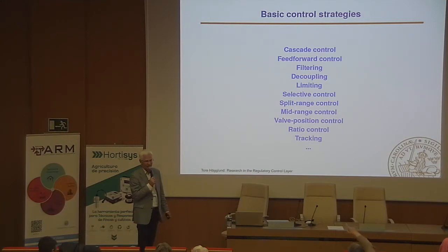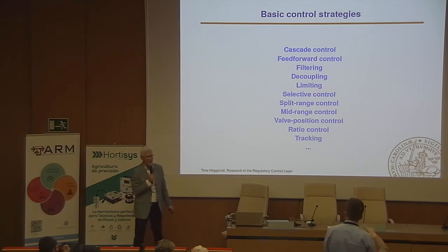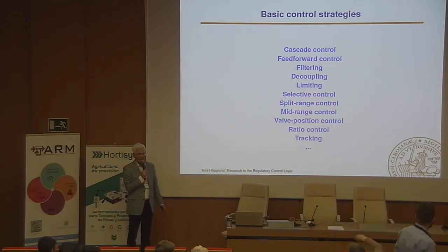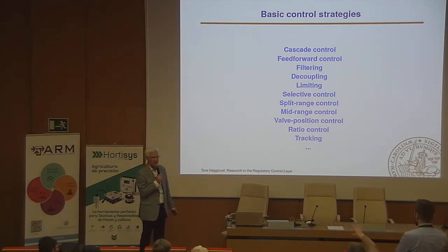Yeah, but for instance, the cascade control, and this is very important from my point of view, the only simple rule that we explain to our students is: in the internal loop, you provide a proportional controller, and then you give all the regulatory capability to the external loop, providing a PI controller. You have 3 parameters, but I think that we can do more in this kind of control loop, because in many, many occasions, cascade control is very important in process control. You can find many cascade controls in the different PID schemes, and probably there are novel tunings, and we can do a better job in order to improve this kind of basic control strategy.